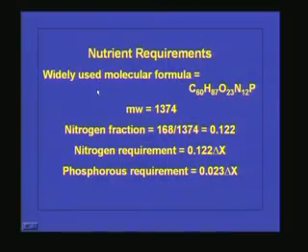So if the microorganisms have to grow properly, we have to supply these nutrients adequately for cell growth. Whenever we take the microorganisms or the sludge and burn it, all the carbon will be converted to carbon dioxide, nitrogen will be converted to nitrogen gas, and hydrogen will be converted to H2O. The remaining ash contains the micro and macronutrients present in the system. So how can we find out the nutrient requirement in the system? Here also we have to use the empirical formula for the microbial system.